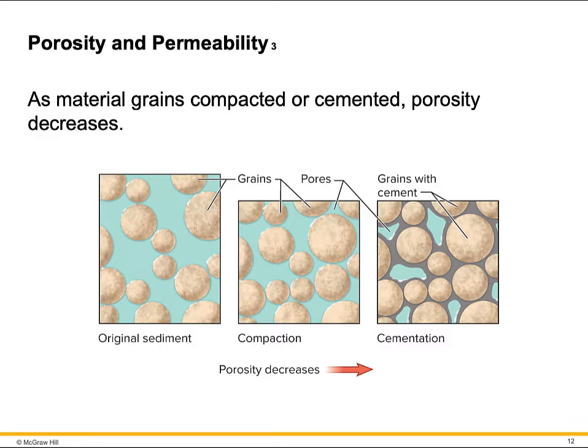Porosity is greater in unconsolidated materials like sand and gravel. They're more porous than sandstone or a conglomerate. The groundwater that can drain from a rock or sediment is called the specific yield. Specific yield is porosity minus specific retention. The specific retention is the water on the surface of grains that will not flow through the material. That is, it's stuck on the grain surfaces. The specific yield of fine-grained material is low, even though their porosity can be high.